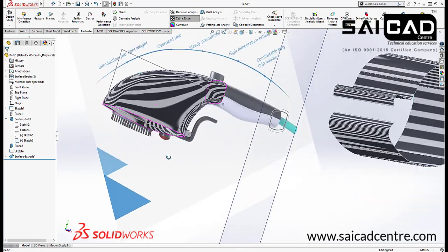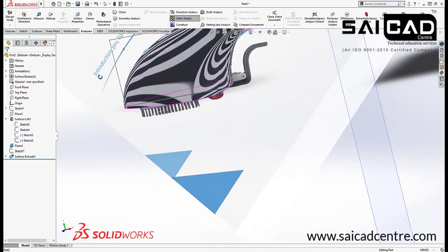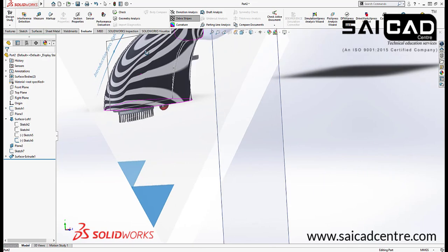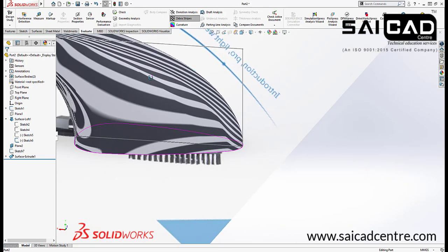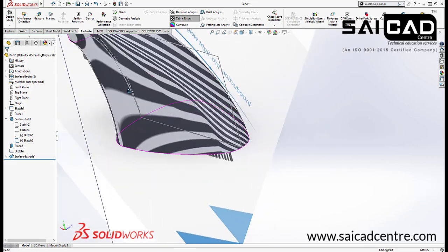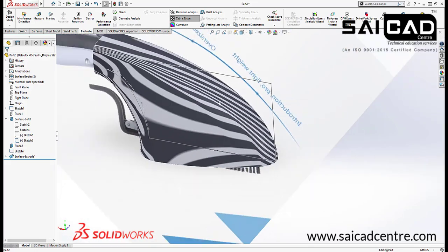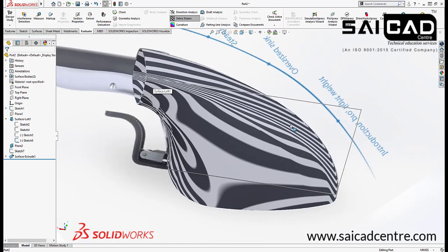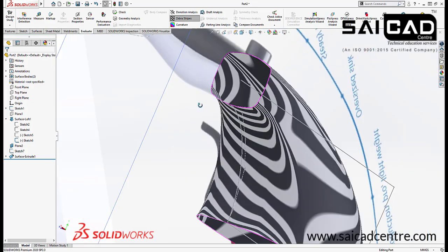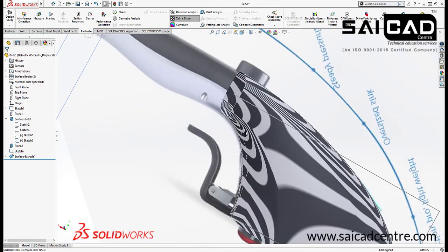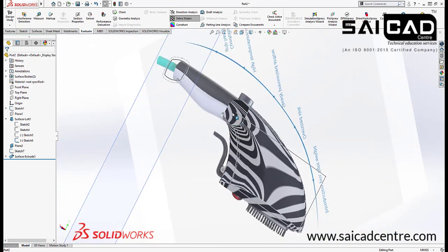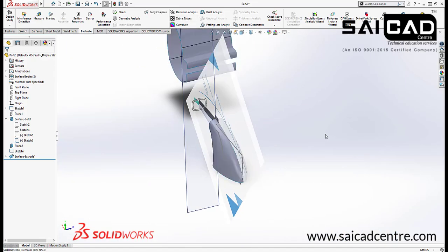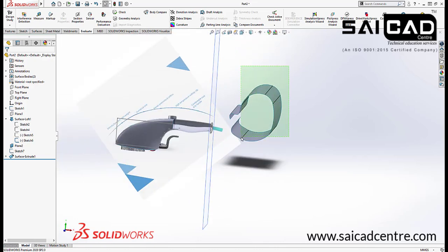So if you see the object that I have created, you can see that object is fine. We have the smooth curves. We have a little bit here if you notice here, but if I rotate, you can see we got the smoothness. Okay, right here you can see we got the smoothness. We don't have the uneven shape because we have created it with the help of some curves. All the curves are tangent or the curvature continuous. So like that we have to create everything properly.